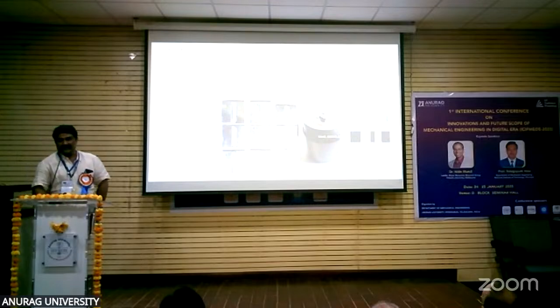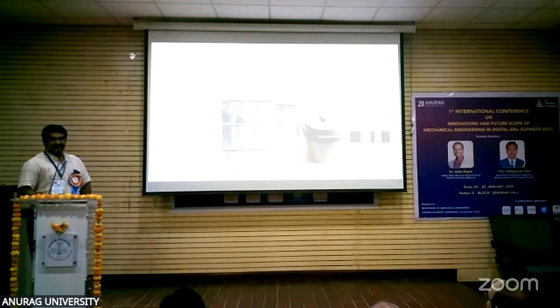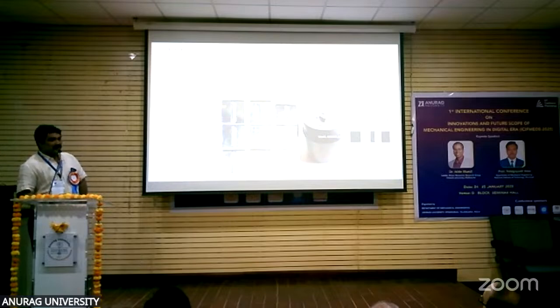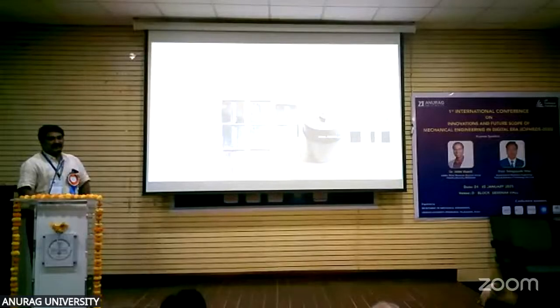Tool material. Generally the tool material used is H13 steel, but in this case we are using titanium and aluminum, with 25% aluminum material. This material is selected because it has good temperature resistance and corrosion resistance. The melting temperatures of the aluminum and the tool metal are very different, so that's why we are selecting this material for the friction stir welding process.